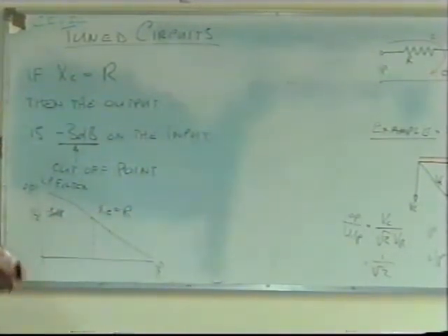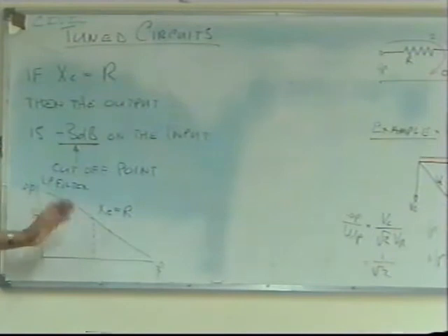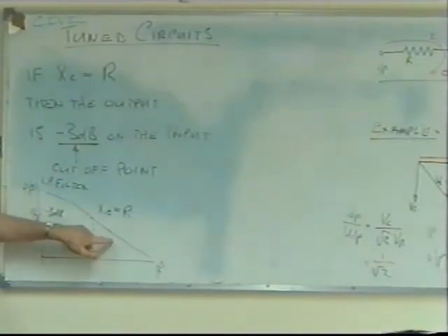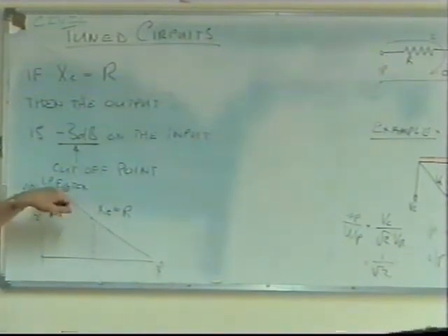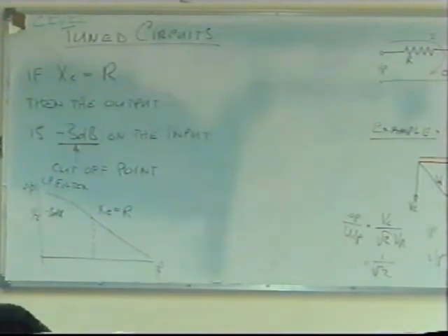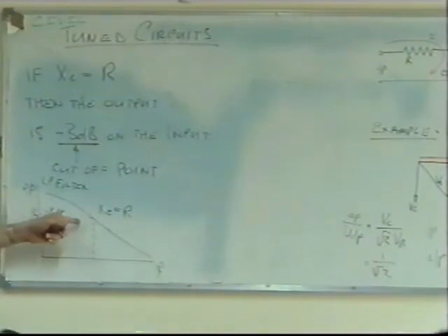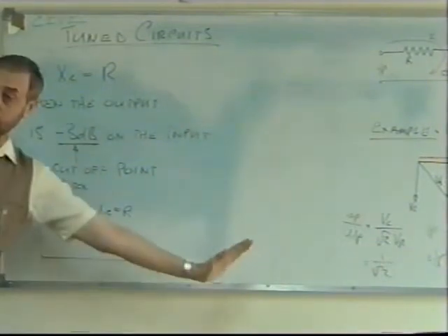It's called a cutoff point. Now, it's not very clear why it's called cutoff, but what they're saying is that it's a point in our graph. Anything above that frequency, the signal is rejected. Anything below that frequency, the signal is accepted. I used these 2 words last week, or the week before, to describe the cutoff frequency. It's a low-pass filter. These are low frequencies, these are high frequencies. So we get a better output power at lower frequencies and lower output power at higher frequencies.